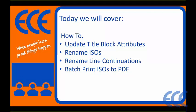As I mentioned, you can also rename these ISOs. So if your current isogen setup is not spitting them out the way you're liking, or it doesn't fit the client requirements, maybe it needs to go into a document management system or something, we can rename those ISOs. And if you're going to rename them, it makes sense to rename those continuations as well. So we have the capability to do that as well.